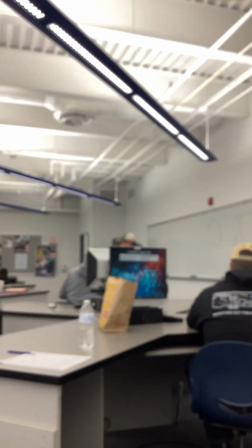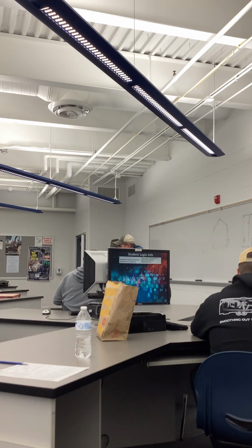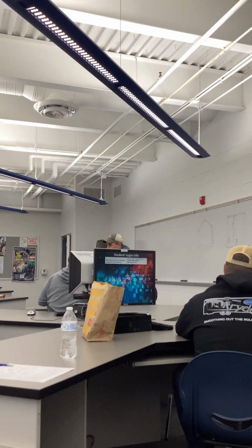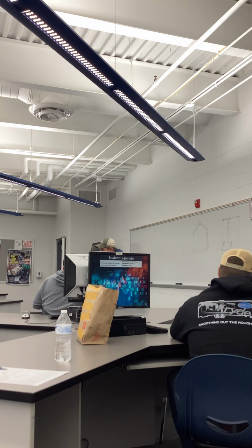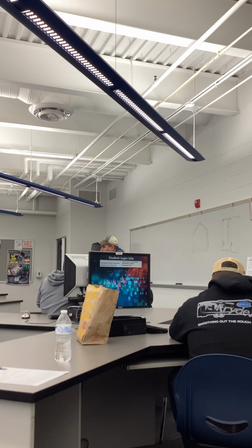For the most part. So in an attic situation, we want to have R38, R40. I want to say R38 is what they recommend. I have to double check. Over like R50 is complete waste.